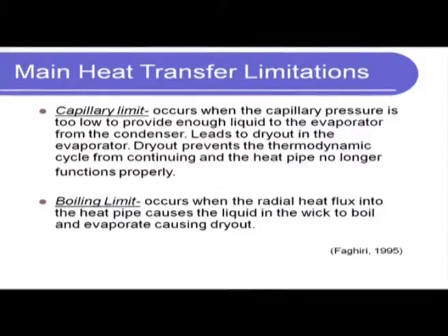Okay. So, this was a mathematical analysis and gives us the maximum amount of heat transport that can happen inside a heat pipe. And again recall, this is a good definition definitely. Another thumb rule is, this is for a straight pipe, but many a times you saw some of these figures in a laptop or for de-icing, there are bends. Any time you have a bend, the transport capability goes down. Okay. So, with bends, with narrowing of cross section etc., the transport capability does go down, all right. Okay. So, quickly now let us go over to some of the limits. So, this is maximum heat transport capability, we have seen that, but what are the limits?